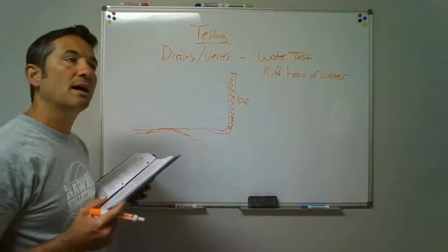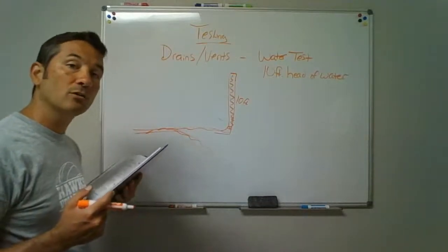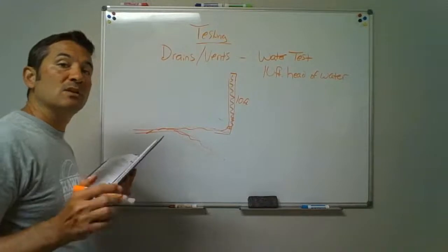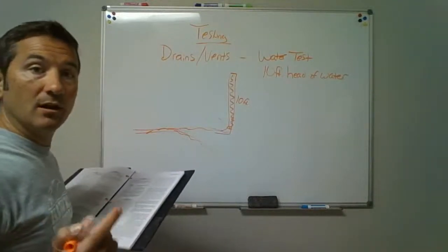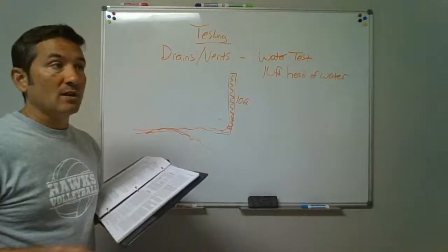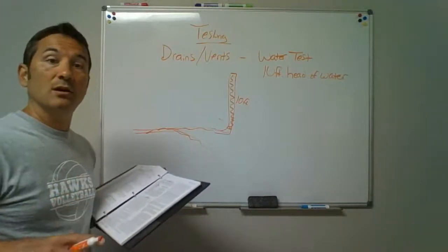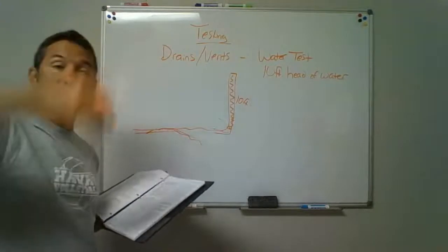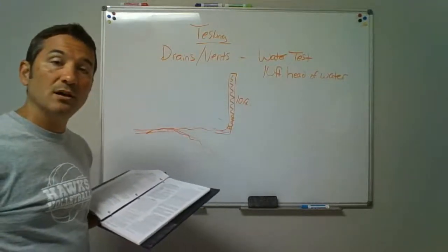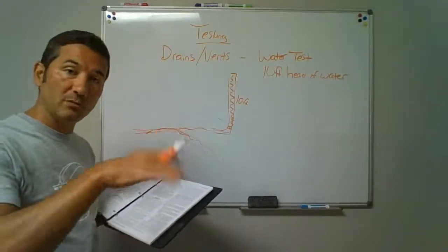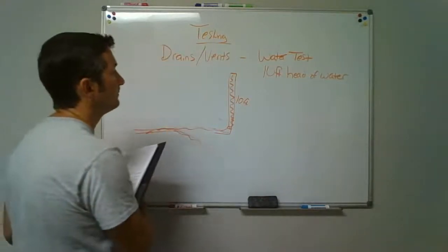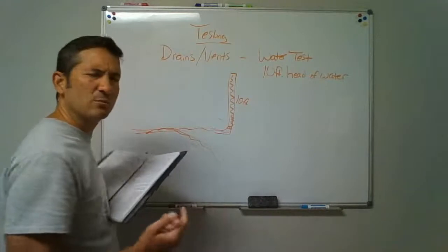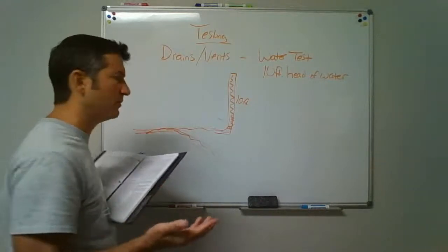They will let you get by with, if you're doing an add-on, a little remodel or something like that, and you say, hey, there's no way I'm going to get this out of here. I'm just adding on a little island section. I can't stick a 10-foot pipe. That would be somebody's existing house. They will let you come up 3 foot and make provision for that. On new construction, they're going to be looking for that 10-foot head. Okay, so if you read that and were confused, it says something about going up 3 foot. Well, that's what it is.